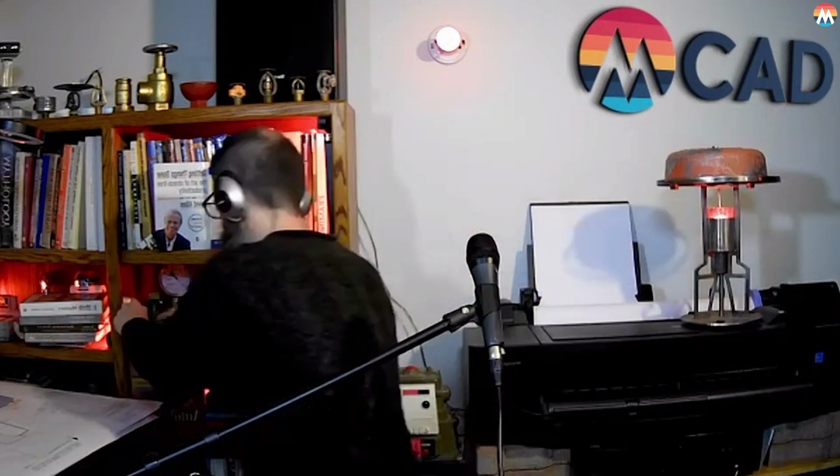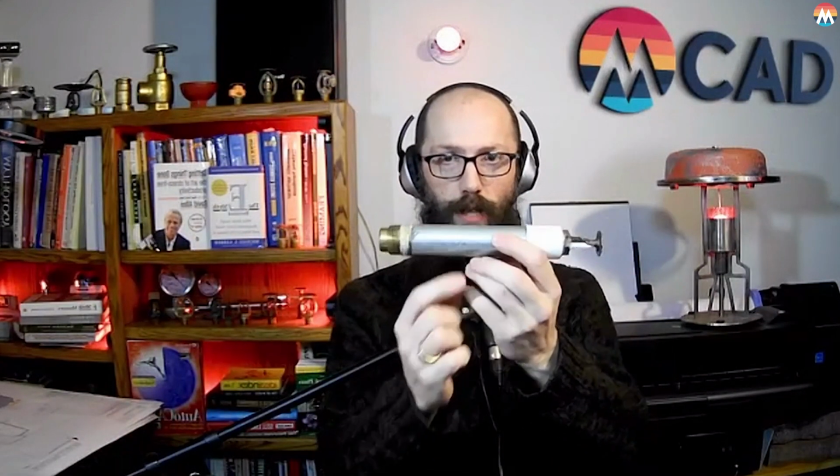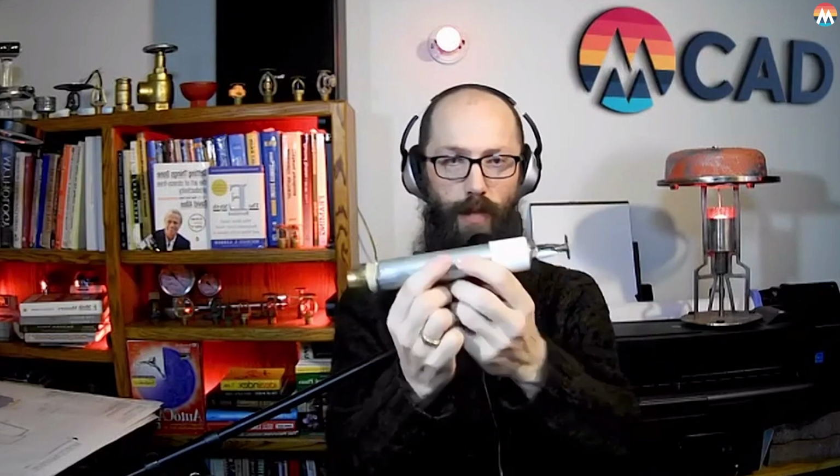And then we can also use what are called dry barrel sprinklers, where the barrel is dry but you can connect it to a wet sprinkler. So you can have a wet system inside a heated space and then pop them out the wall to cover an unheated space. This is a short one right here. You would just put this out the wall into the hood. This one happens to be a pendant, so it's supposed to be in this position, but sidewall ones would be the same thing. You pop this out the wall, this is a heated area, and out here it's freezing.